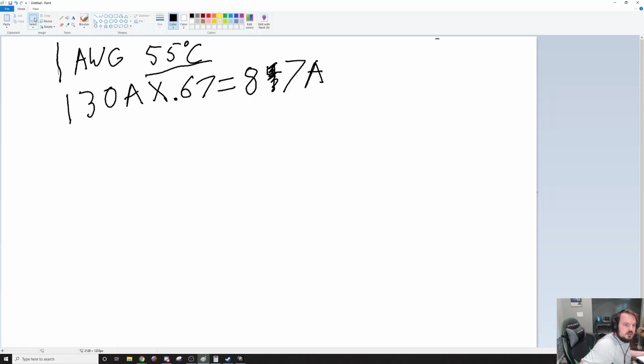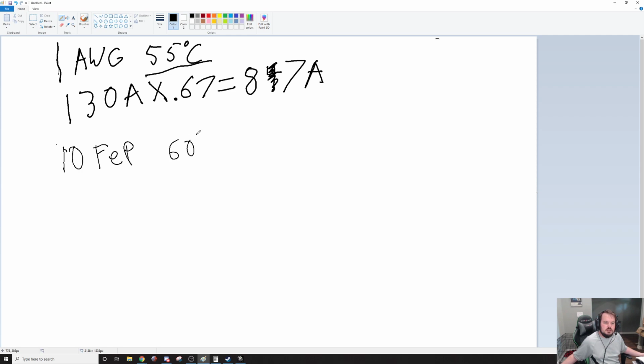So let's clear. I can do it down here. 10 at 60 degrees Celsius. Now we have 60 amps, and we have to get our multiplier.